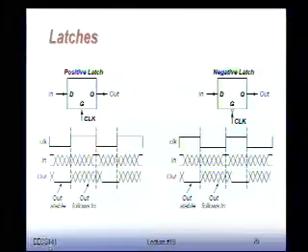Okay, so this shows the same thing. This is a latch. When the clock is low, the output remains constant, independent of what's happening with the input, which might go up and down and up and down. However, when the clock is high, you can see that the output follows directly what the input does.